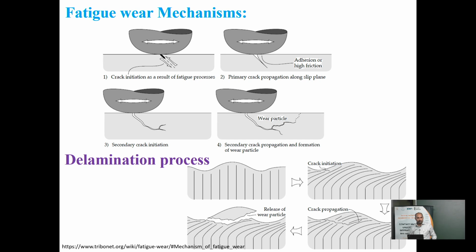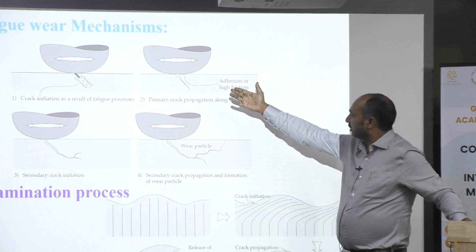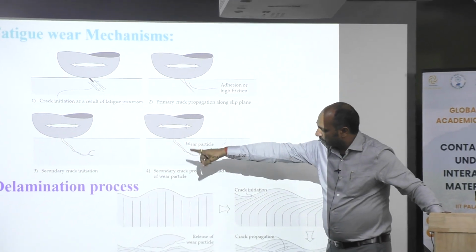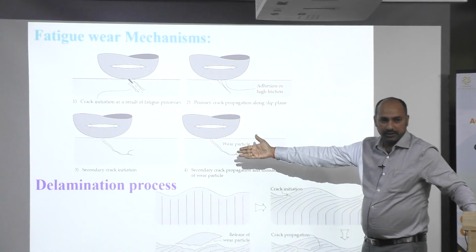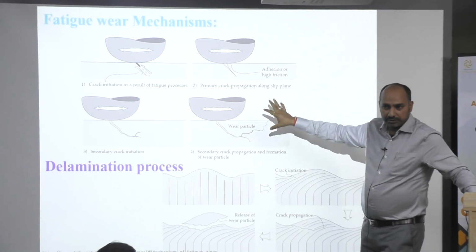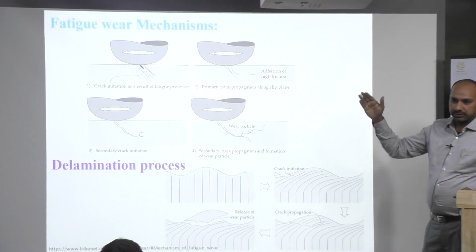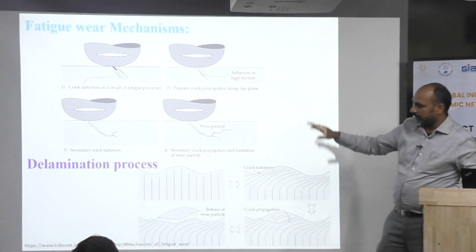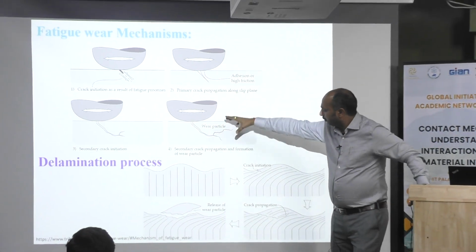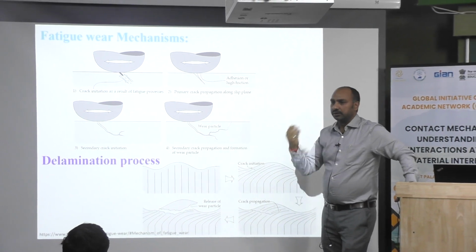Talking about the wear mechanism for ceramics, it is crack initiation, crack propagation, and then fracture. Once you go for repetitive action, a crack gets initiated, then it propagates, and a secondary crack gets generated and reaches the surface. We will see this in actuality when we analyze the subsurface, and I will let you know. Then this complete part will come out as a chunk and get fractured.